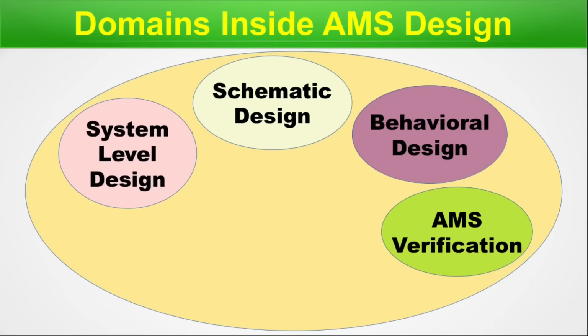Next, we have the very critical stage, that is the mixed signal verification. Here, we have a special kind of simulator pair, that is analog simulator plus digital simulator working together and handshaking for cross-domain signal transaction. In such kind of verification, the analog simulator such as SPICE or Verilog-A simulates the analog circuit block. At the same time, the digital simulator such as Verilog or SV simulator simulates the digital block from the entire design.